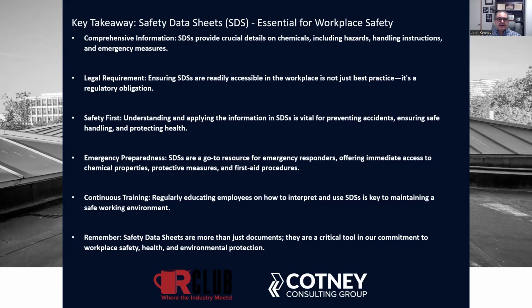Emergency preparedness: SDSs are a go-to resource for emergency responders, offering immediate access to chemical properties, protective measures, and first aid procedures. So again, if somebody ingests something and has to go to the hospital, you want to make sure the hospital knows what's in that chemical by having these readily available. Continuous training: regularly educating employees on how to interpret and use these SDSs is key to maintaining a safe working environment. Always remember, SDS sheets are more than just documents. They are a critical tool in our commitment to workplace safety, health, and environmental protection.